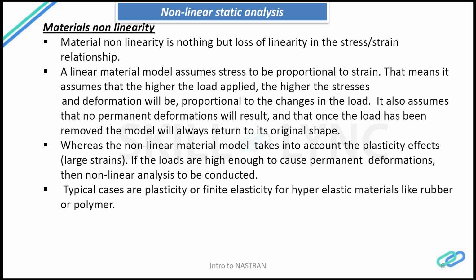And so if you are using a nonlinear material, if the component is made from a combination of metals, which are mostly linear, and nonlinear metals or nonlinear elastomers and polymers, then it is advisable to run the nonlinear FEA to generate accurate stresses and understand the accurate behavior of the structure. Typical cases are plasticity and finite elasticity for hyperelastic materials like rubber and polymer.